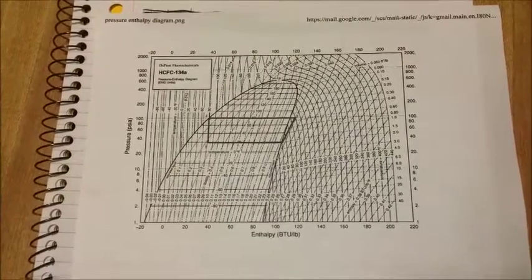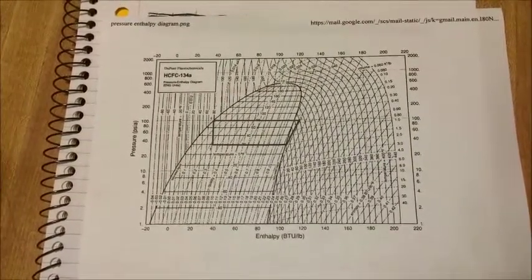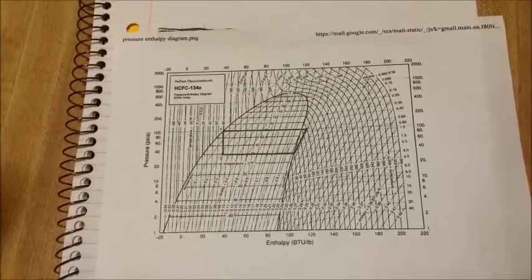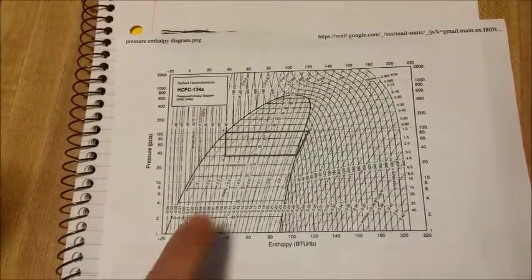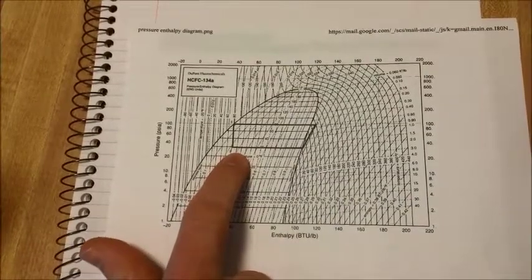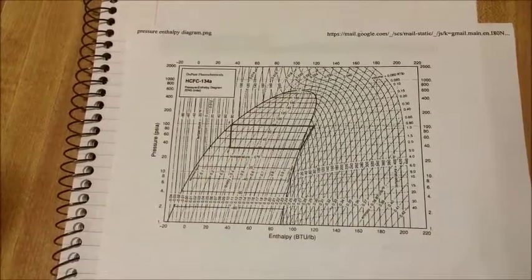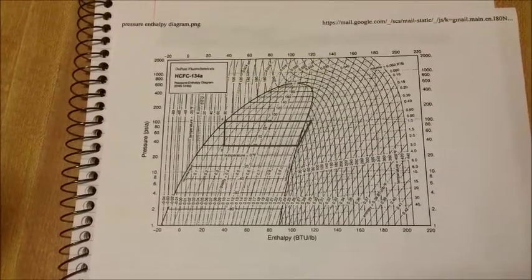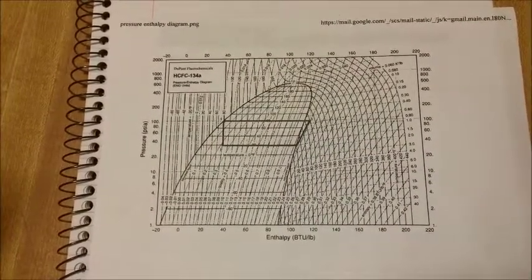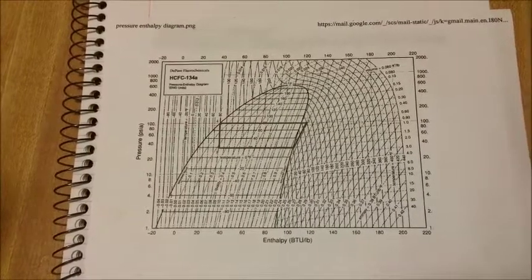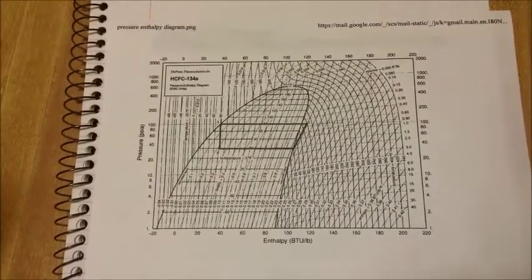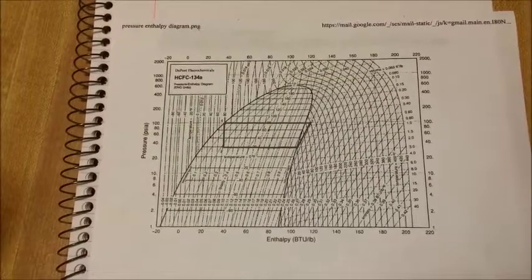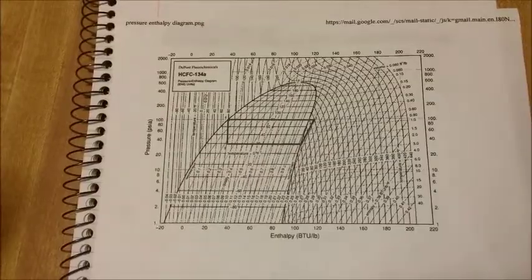The next assumption we make is that the change in enthalpy across the throttling valve is 0. This allows us to find the temperature of the stream entering the evaporator, which happens to be the same temperature at which the evaporator operates. We then solve for the change in enthalpy and divide it by the efficiency of the compressor to find the work done. We add this work to the enthalpy of the entering stream to find the enthalpy of the exiting stream. Now all that is left is to solve for the power required by the compressor.